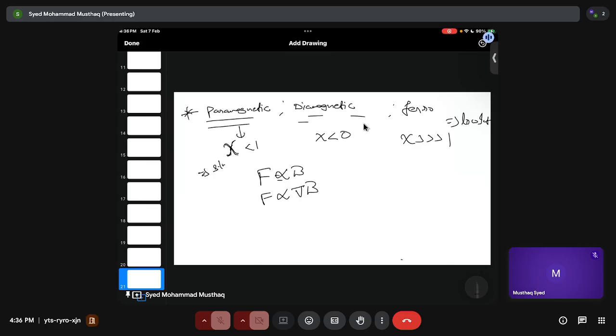So even if you increase the B from like 1 Tesla to 2 Tesla, the response is small. But if you have a large gradient, even if you apply small magnetic fields, if your gradient is large, that means dou B by dou X is large, then your paramagnetic materials can be attracted to them, right? So that's the basic difference. That's why we have low intensity, high intensity, low gradient and high gradient magnetic separation, because of these paramagnetic particles, right?